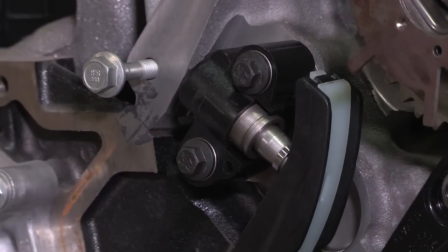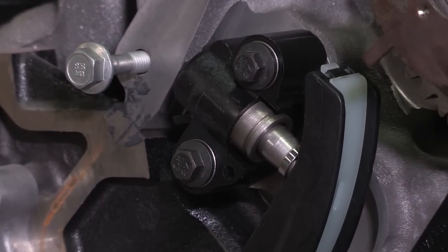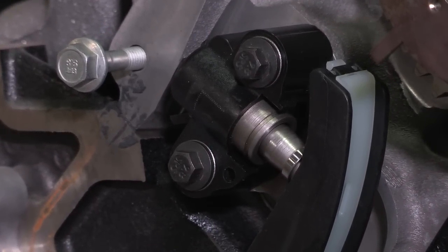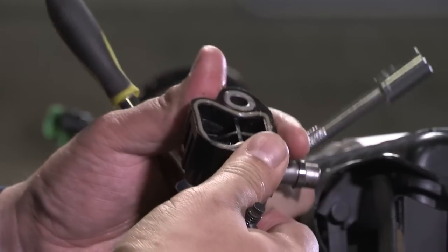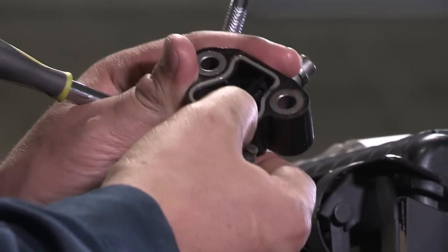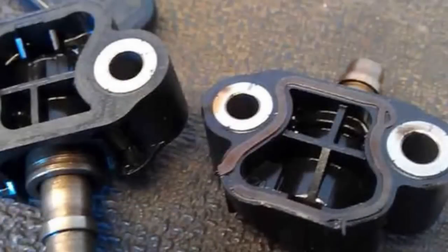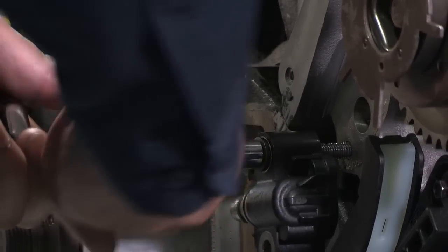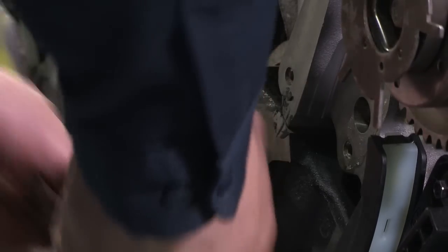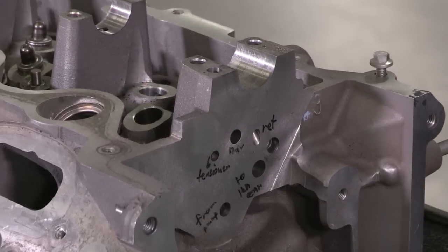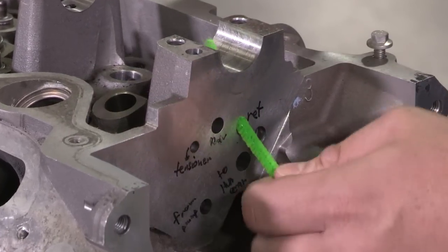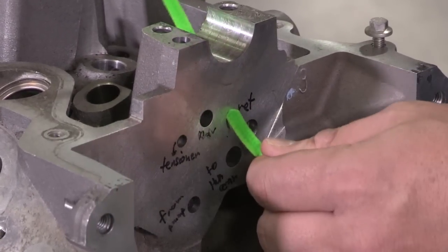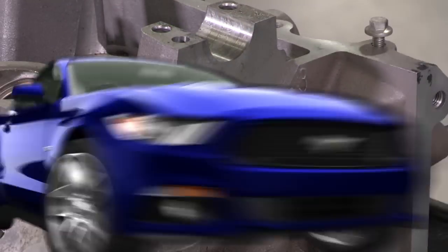One area that many techs mistakenly think there might be excessive bleed-off is the chain tensioner. The seal on the chain tensioner is only a dam to prevent noise on cold starts. So if you see a torn seal here and you think only replacing the chain tensioner will fix the VCT issue, it's a myth. Next, let's take a look at possible areas of restriction that could be the cause of VCT issues.